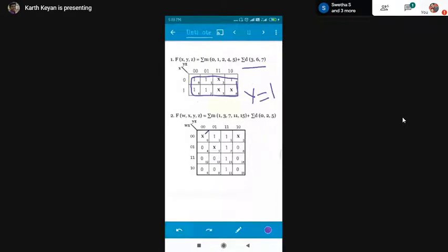Okay, so why do we discuss this don't care? With the help of the don't care, we are going to enlarge our group, and automatically the number of variables gets reduced. Here we'll go for the second case. We have this one 4-cell. Only one is missing. With the help of the don't care, I'm going to make it one more 4-cell. So don't bother about 2 and 0, these two.